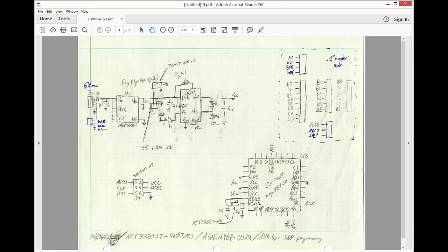And then we're going to have a boost converter. I wanted to try to find a multiple amp boost converter, but it turned out to be really a challenge when I was dealing with 3.7 volts to find one that could do multiple amps as well as be a simple implementation. Because I knew I was also going to use this design for doing this series of how to use KiCad. So I ended up with this part, which is the MCP 1642-something or other. We'll definitely find that in more detail as we look at the data sheets.